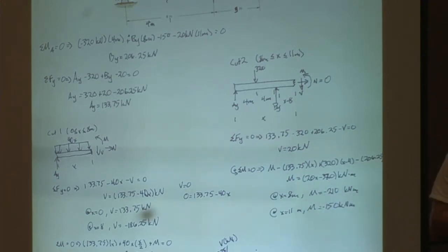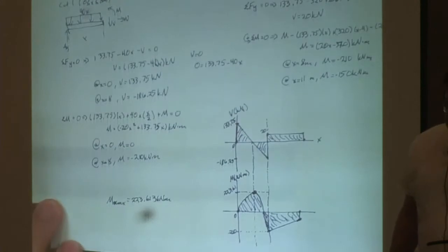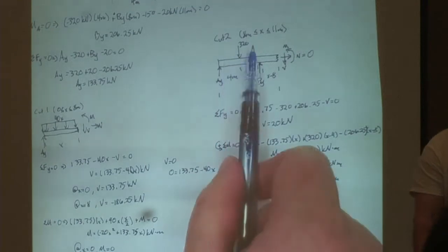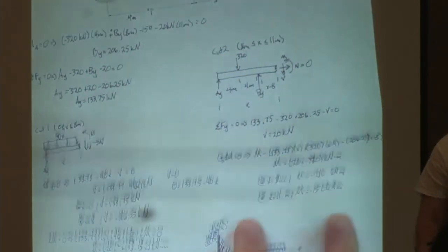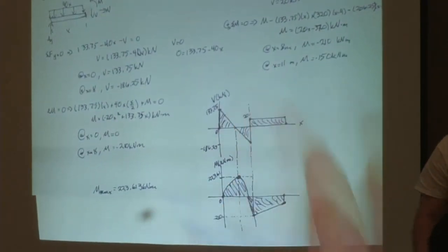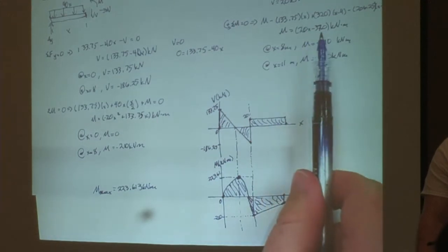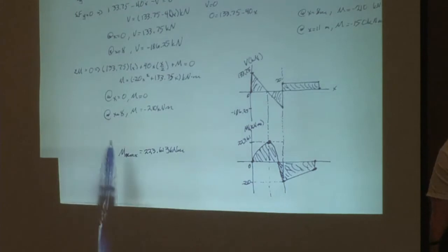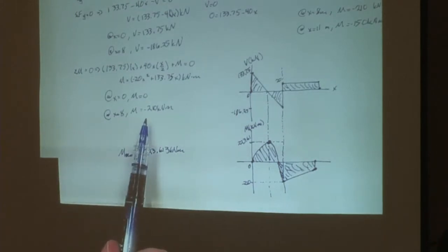Sorry. But why is it at the cross in the middle negative 210 for the parabola on the left side? Does it make sense? Why are you starting at negative 210 for the parabola, but then that one's supposed to start at negative 370? So this starts at 8, right? So that starts at 8, not 0. So if you put 0 in there, yeah, we would start at negative 370, but we don't. So over here, when we finished at 8, the moment stopped at negative 210.